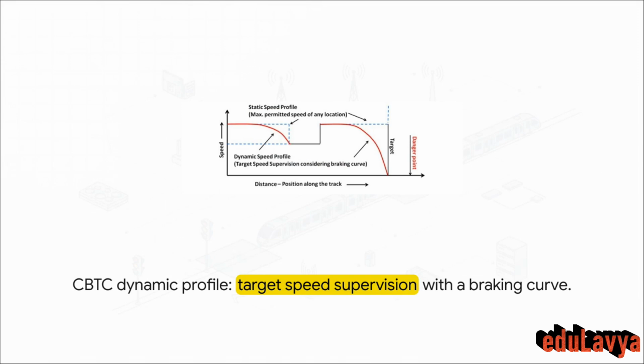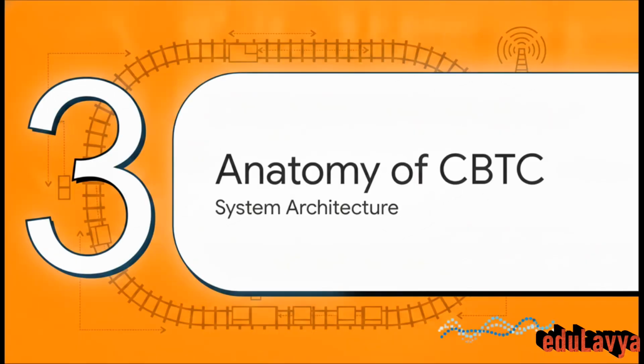But with CBTC, we get a dynamic speed profile. The system is constantly crunching the numbers in real time to calculate safe braking curves. It effectively moves the safety authority right along with the train. You can kind of think of it like adaptive cruise control on the highway. It lets trains safely ride much closer together simply because the safety buffer adapts continuously to the train's actual speed and exact location.